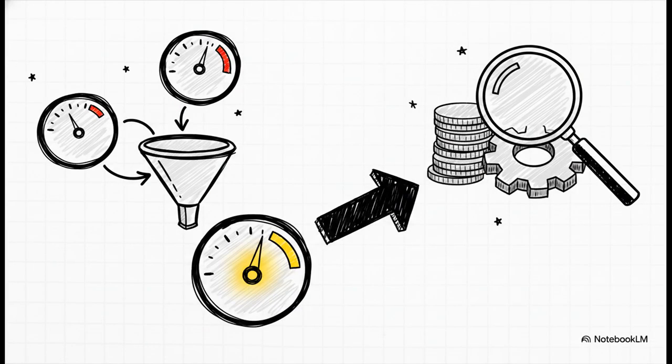Okay, so here is where it all comes together. You multiply severity by occurrence by detection to calculate the RPN, or the risk priority number. This resulting number is absolutely crucial. It's your guiding light. It dictates exactly where a plant should prioritize its safety improvements and allocate its budget. You don't have to guess where to spend your resources anymore. The RPN tells you mathematically exactly where your highest risks live.